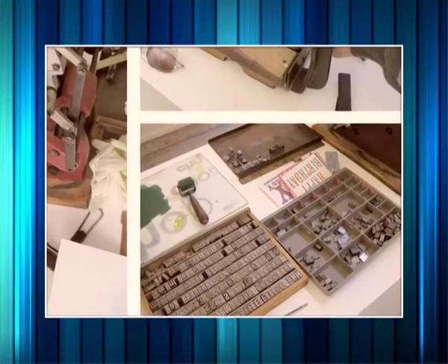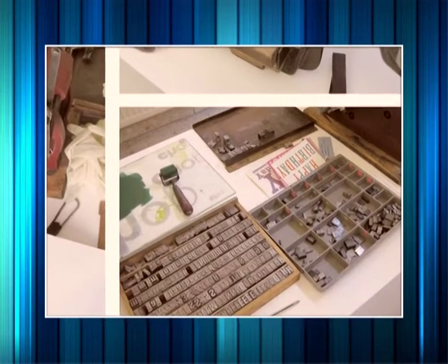Copies of forms were cast when anticipating subsequent printings of a text, freeing the costly type for other work. In this process, called stereotyping, the entire form is pressed into a fine matrix such as plaster of Paris or papier-mâché, called flong, to create a positive, from which the stereotype form was cast of type metal.